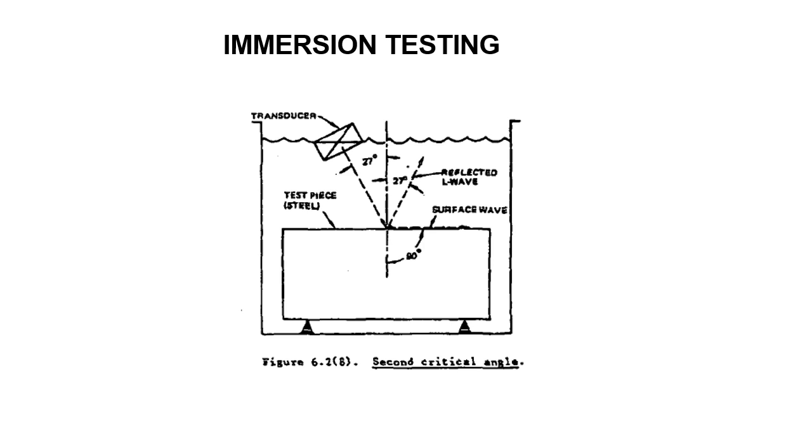Because of this distance between the transducer and the specimen, near field and dead zone type effects are usually minimal for immersion type testing. Also, with the transducer separated from the specimen and the coupling being automatic, the transducer is reasonably free to move, and therefore most automatic scanning methods are associated with the immersion testing method.